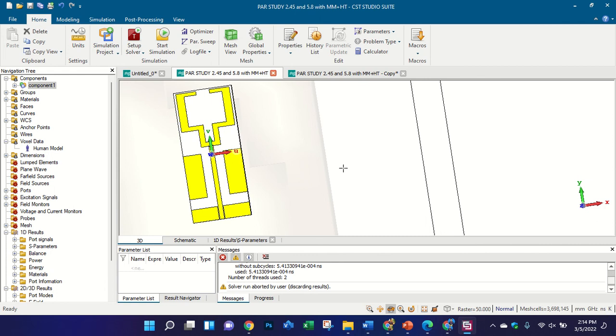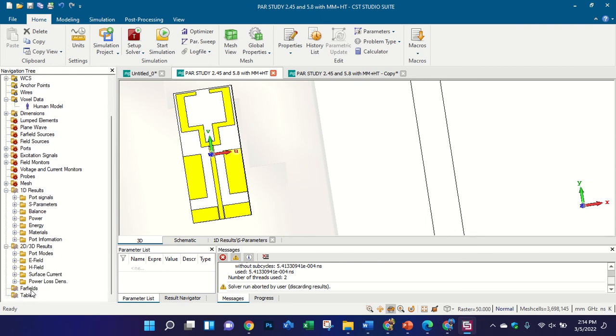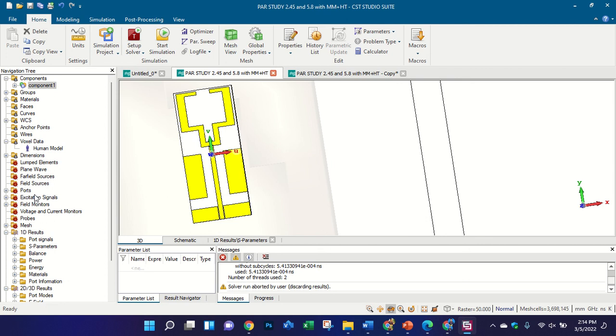It depends on the antenna application. If you want a MIMO antenna, then your parameters, the S-parameters, the surface current and the far field are the same in every case. These are the most commonly used parameters on which your antenna is based. If you use other parameters according to the application, you need to add more results. In a MIMO antenna you add S21, ECC, CCL, and many other parameters. In normal cases you add only S11, efficiency and gain, because only these depend on the design and the efficiency of the design in the working condition.